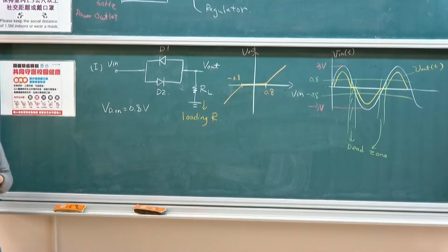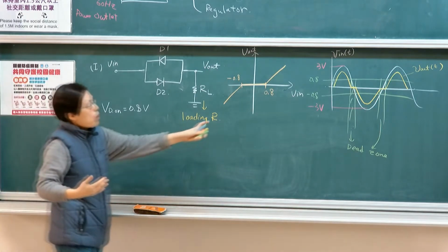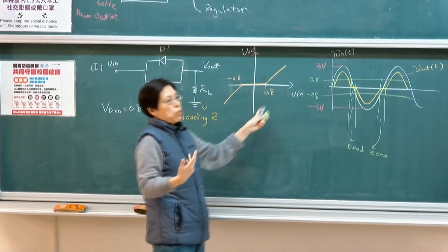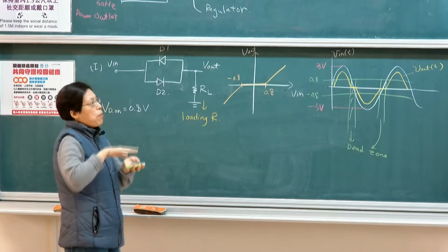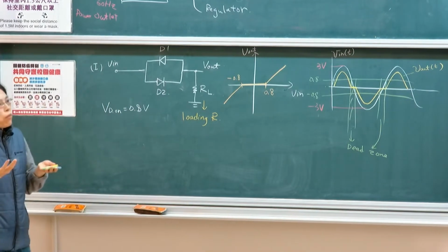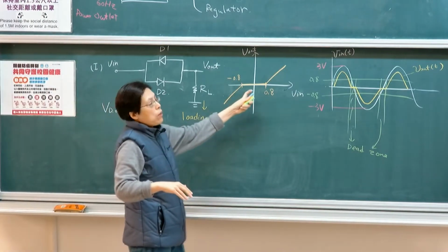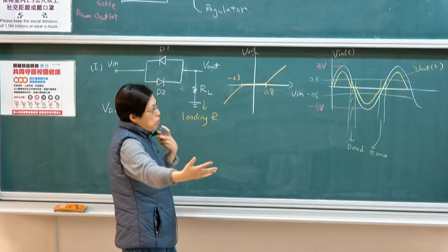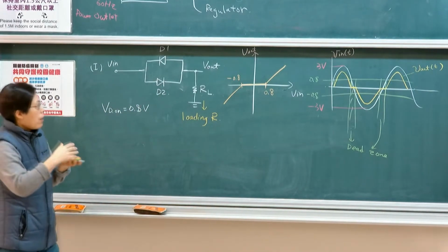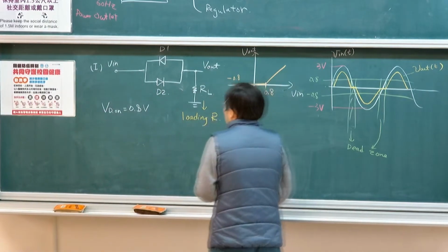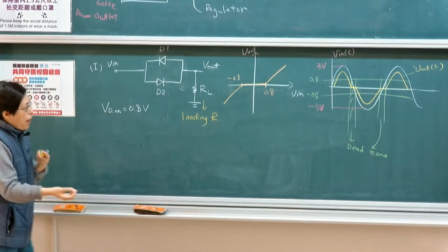First, if you look at this plot, it basically allows you to sense a signal. It's sort of like a filtering operation. It allows only signals passing through the threshold. For example, here I'm setting my threshold to 0.8. It only allows signal when it passes 0.8. If my signal is very low, for example 0.5, you will see a flat line because it will lie within the dead zone for the whole period. So this is sort of a detection circuit: when it exceeds a certain level, the signal will pass.